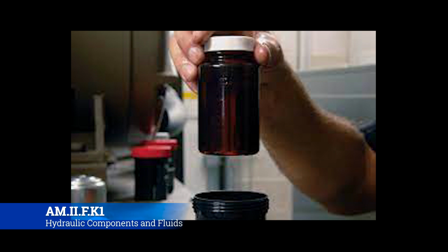Now contaminants break down into two families. One is abrasives, so this is just chips and dirt and junk in there that erode the pumps and the equipment that the hydraulic fluid comes in contact with, and then non-abrasives. I've actually seen this probably more often than abrasives, where you'll have some little bits of almost black flaky stuff that'll develop inside of that hydraulic fluid, and that's what filters are for, to catch those types of things and filter them out.